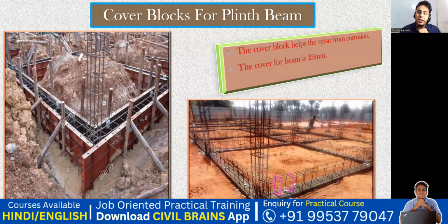So for this stirrup, what diameter are you supposed to use? You're supposed to use an 8 diameter bar. And what is the center to center spacing you're supposed to keep? It is mentioned in the drawing, that is 7 inches center to center spacing. 7 inches comes out to be 175 mm, because 1 inch is 25 mm. So 25 into 7 comes out to be 175 mm. So this spacing will be 175 mm center to center, or 7 inches.